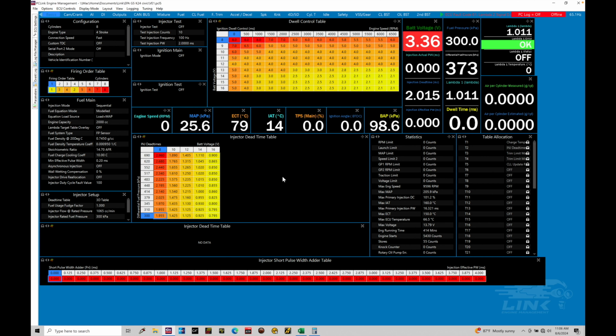It actually takes a lot of the setup and work out of the old traditional standard style knock control that we've talked about already, specifically the knock threshold table and a lot of the other details for programming. So it simplifies setting up the knock control, and it works fairly well for most engines I've tested it on. What we're going to do is go through some of the settings and configurations and actually configure it in a file here. Then we're going to take a look at two example calibration files and two data log files so we can get a little bit better sense of how this all works and fits together.